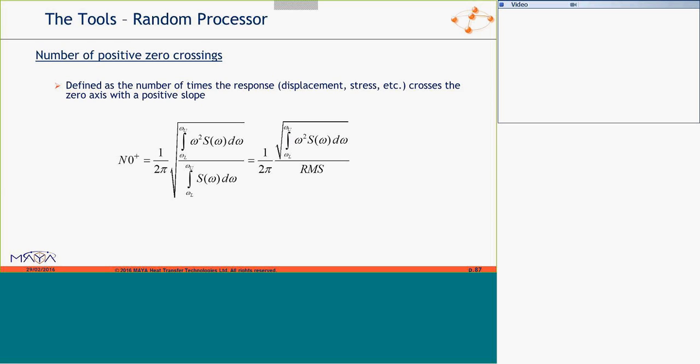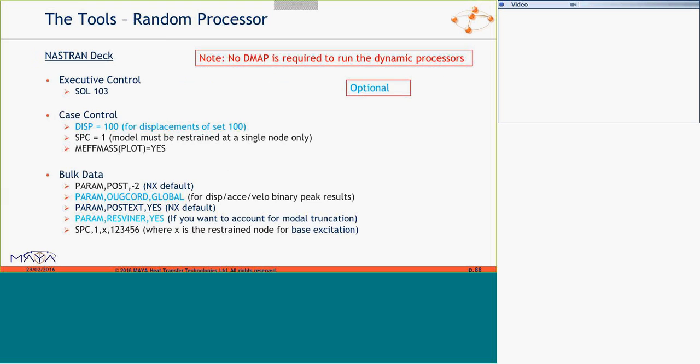If you've got a single mode that's creating all your stresses or your displacement, then okay with the method you described. But if you have more than one mode that's got significant energy, then it's not accurate. So mine is this result, which is freely available to you.